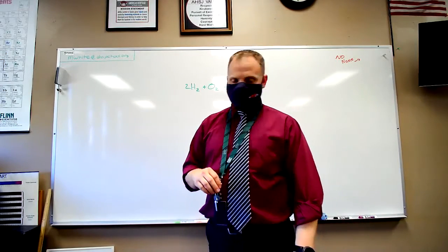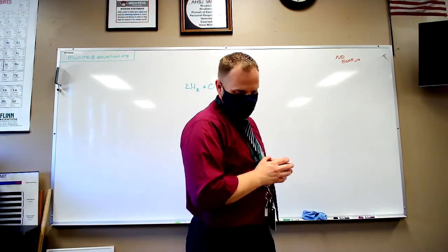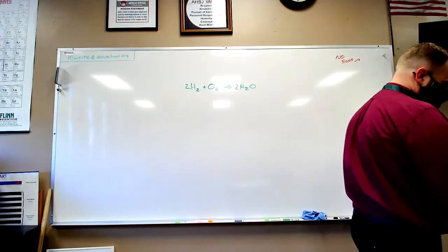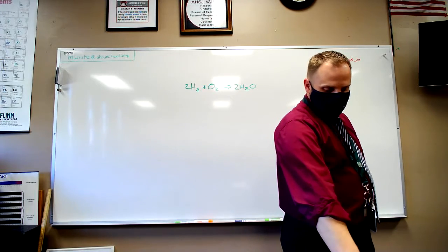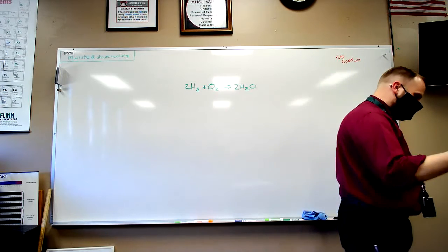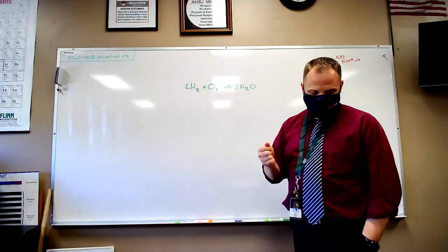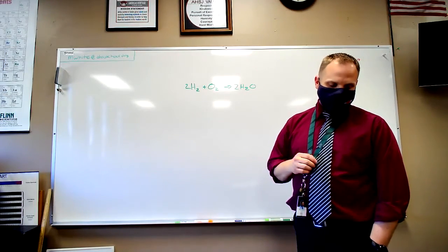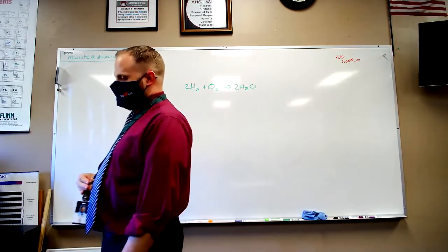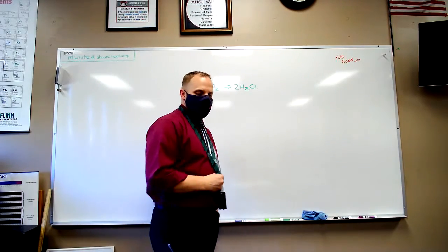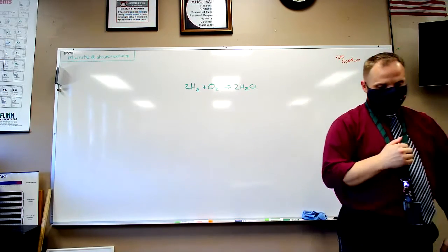The third way that the book talks about preventing corrosion is a process called galvanization. Galvanization is a lot like painting, except instead of painting something, we dip this object in molten zinc. Or we can use a process called electroplating. We haven't talked about that yet. We'll talk about that next time. But basically, we're taking iron and we're coating it in zinc.